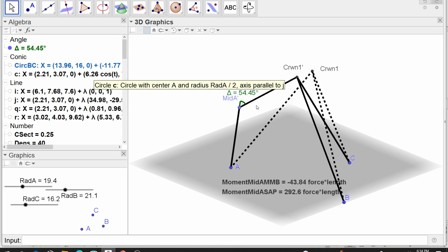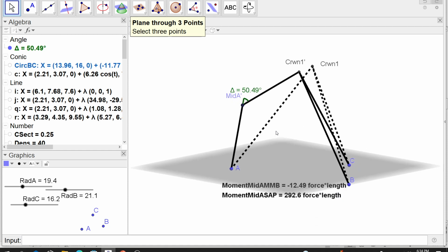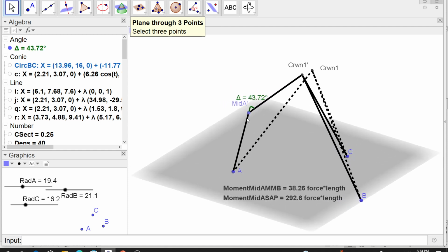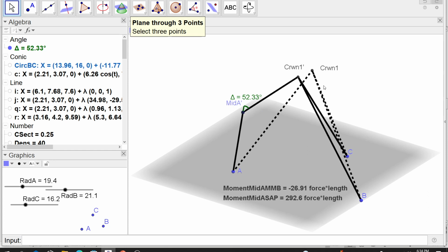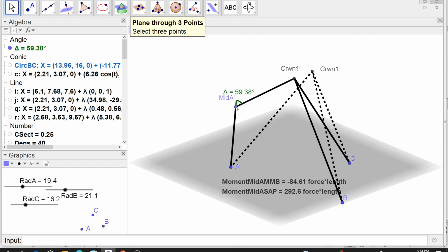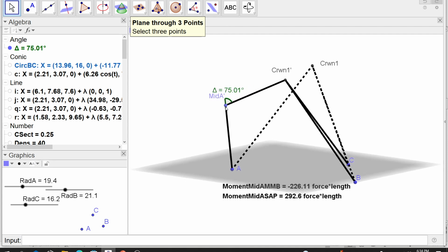For instance, do these sticks on this side of the crown, do they contribute to the bending? And this is the best part of this tutorial, I think, because the answer is no, they don't, but it sure looks like they do. And the reason why it looks like they do is this: if I put the weight of strut C at the midpoint of strut C, during this perturbation, that midpoint moved. You could see it move vertically.